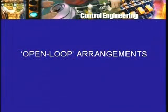So we can compare the two situations, one of which can be called open loop, though strictly speaking it is not open loop, but what we mean is something like this. Suppose we took this system and got rid of this error detector and tacho generator and reference signal, etc., and just gave a constant input at that ET point. Say we kept ET constant at 1.15 volts, so that the armature voltage was 230 volts. So in this sense the loop has been broken. So in this sense, open loop.